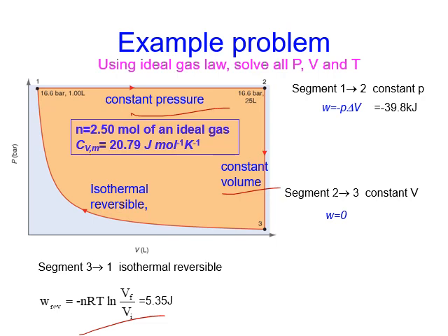Well, let's start with constant volume. If volume is constant, work is zero, so heat equals internal energy change. Both are calculated by CV delta T.